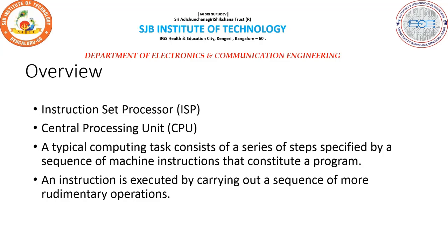To execute a program, the processor fetches one instruction at a time and performs the operation specified. Instructions are fetched from successive memory locations until a branch or a jump instruction is encountered. The processor keeps track of the address of the memory location containing the next instruction to be fetched using the program counter. After fetching an instruction, the content of the PC is updated to point to the next instruction in the sequence. A branch instruction may load a different value into the PC.